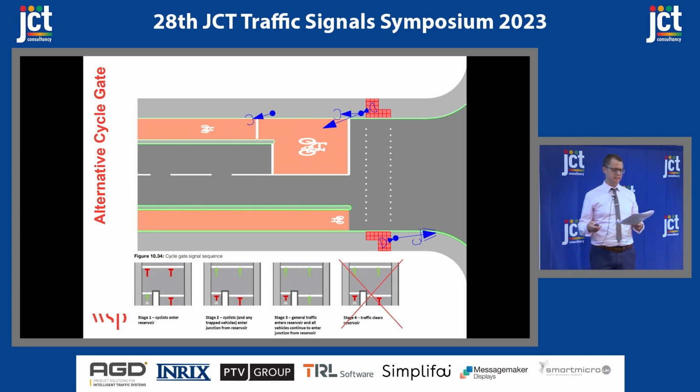We can't replicate stage 4 in this layout, but do we need to? The stop line of the ASL is never more than 7.5 metres away to meet TSRGD, compared with at least 18 metres between stop lines in a traditional cycle gate to meet LTM 120 guidance. So we don't really need the delay anymore between the control of each stop line.